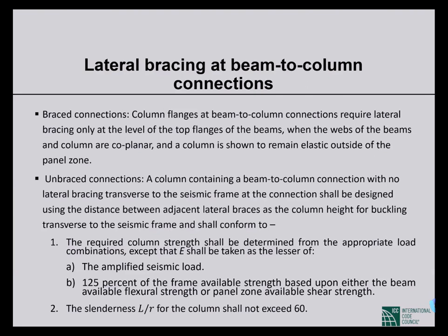So we need to actually have, theoretically, the top flange under compression. That's why there is a chance of buckling. So we have to connect the bracing. We need a separate bracing for the top flange. The connections where we'll provide bracing for the top flange, we'll call that braced connection. Where we'll not use that, we'll call that unbraced connections.